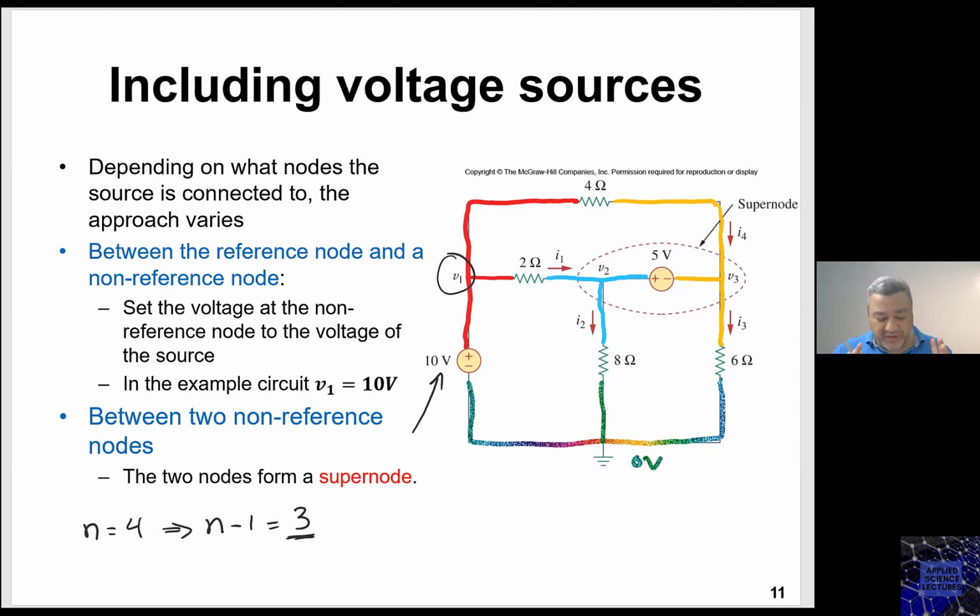If I look at my N minus 1 equations, there are 3 variables, 3 nodes, 3 variables. I'm giving them V1, V2, and V3. But can somebody tell me, what did the existence of the voltage source this way do to my V1?